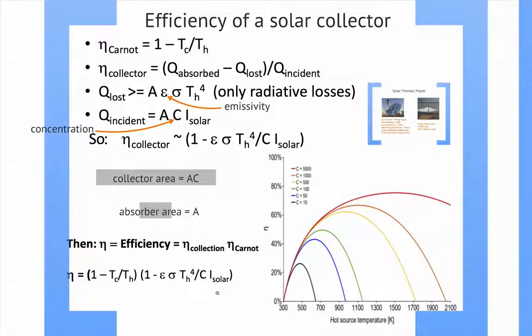So you can see two things competing against each other. That's the most important thing I want you to get out of all these equations. Look at T_h. T_h here has a negative sign, which means that it contributes in a negative fashion. In other words, when this increases, this term decreases. Now here T_h is in the denominator with the negative sign, which means that if T_h increases here, this whole thing increases. And we know from Carnot that if I increase the temperature of the hot body, my efficiency goes up. Those are the two competing things that happen in these two terms.